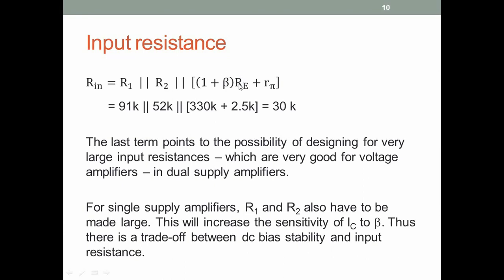So this is like 100 times Re or 200 times Re. So this circuit has the potential of having a very large input resistance if we use dual supply.